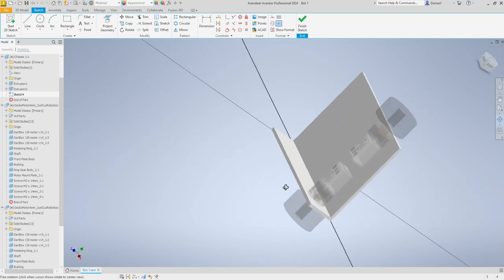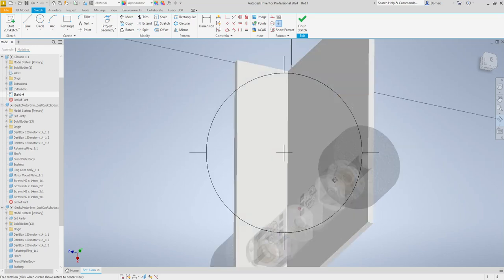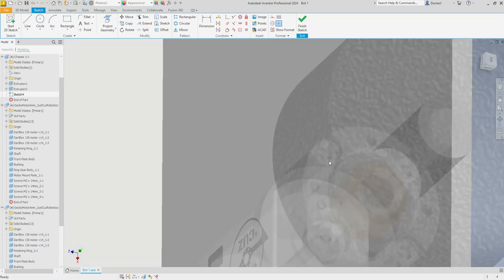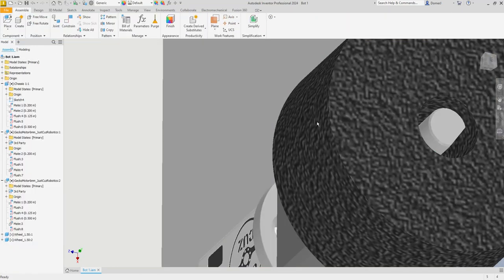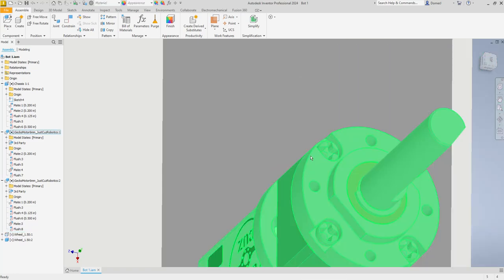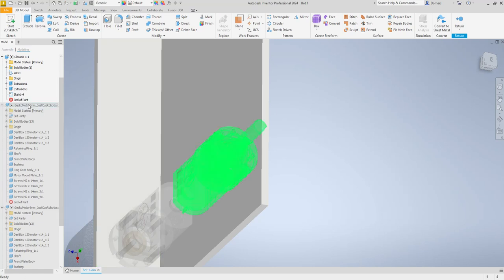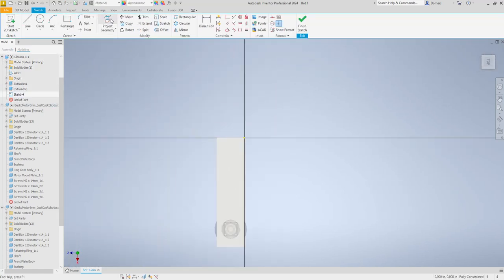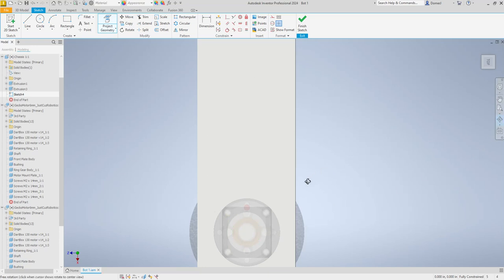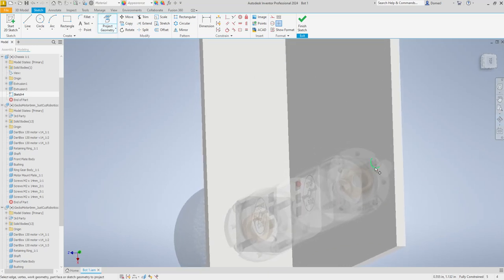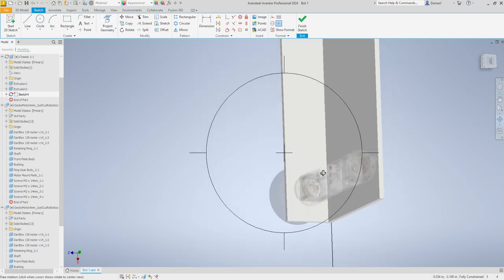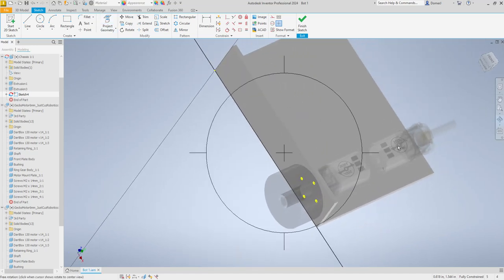So I am going to come over here to this other motor, which should be the same thing, and I'm going to go back to the assembly. I'm going to turn this wheel's visibility off. I'm going to go back into my chassis, back into my sketch, project, and I'm going to do it from this other motor. So the mounts that I want are this hole, this hole, this hole, and that hole, my 4 mount holes to my knowledge. When I come around, you'll see that we pop those holes into that sidewall.